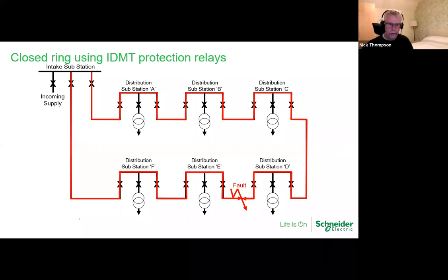And this is one of the challenges of network design, choosing the right equipment for the application. And certainly the amount of current that's going to be fed through that network is going to determine the circuit breaker size in the feeds. But we've also got fault current that is flowing clockwise but also anti-clockwise. So we've got fault current that's traveling in 2 directions.